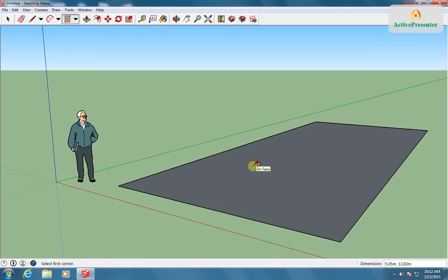To make it 3D, now let's look at the next section of tools over here. There's lots of different stuff up here that lets you grab parts of your shape and move it around almost like a sculptor with clay. For turning a 2D shape into 3D, I want to use the very first one. It's called push and pull.